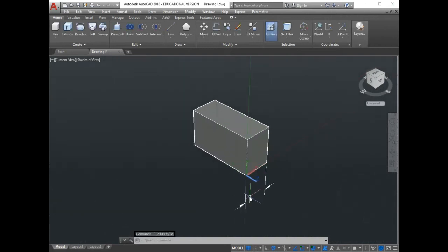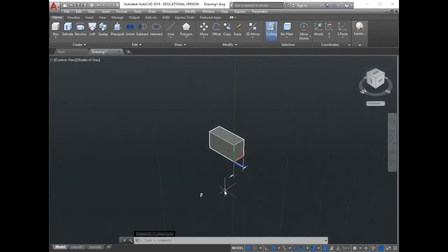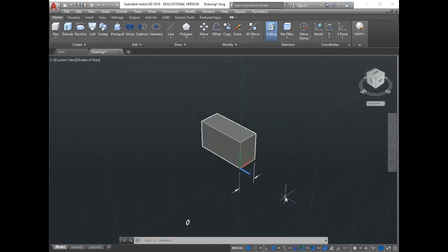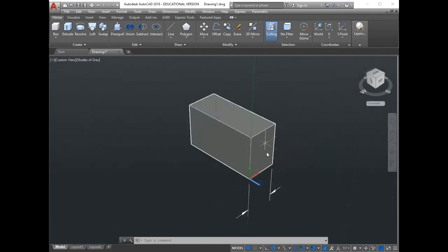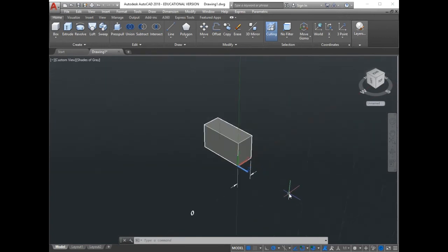Here you go, guys. You see, now you can see your dimension. But there is a mistake, guys, that I made here actually. What is that mistake? When I put the dimension for that box, the dimension is almost like 0.3, 0.4. So if you make approximation, remember that we removed all the zeros for the precision. So usually if you are speaking about 0.2 or 0.3 and you make your rounding, it will take you back to 0, right? This is why I can see the dimension here is equal to 0. You got my point, guys? So let's repeat this one. Okay, that's fine to learn from our mistakes.